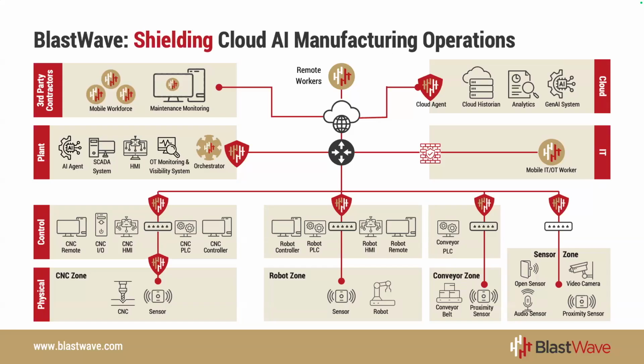But I can also use it to control what protocols and messages are allowed to come into and out of that network. So I may, for example, say that the Gen AI system is only allowed to ingest data coming from my OT environment as a one-way pipe, similar to what you might use with a data diode, to make sure that the Gen AI system can't suddenly start trying to control it, or if it's taken over by someone, start sending JSON or Python or some other API to cause my systems to blow up or to start doing bad things. So it is a way to get a foot in the door.